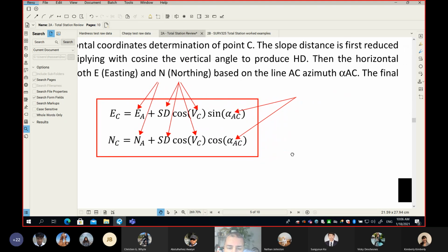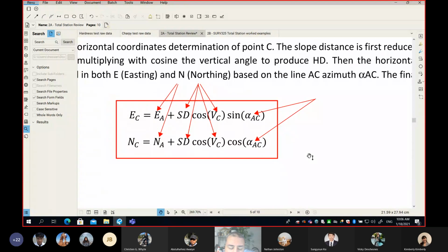Remember this name, backsite. The backsite simply requires two points of known coordinates, where the total station, based on the coordinates, can calculate the azimuth of the line. And if it is able to turn the circle so the reading at this line equals the azimuth, it means that after this process, the 0 of the total station is not randomly oriented on site.